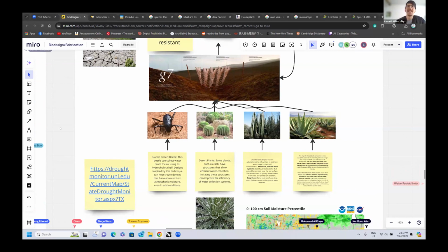Okay, that's super interesting. Yeah, in that case, you can try different geometries and with the different angles, for example, for this element, and with the CFD fluid dynamic simulations, you can check which ones can slow down the wind more, because the slower the wind gets while it's hitting your surface, the more interaction it's gonna get with your surface.